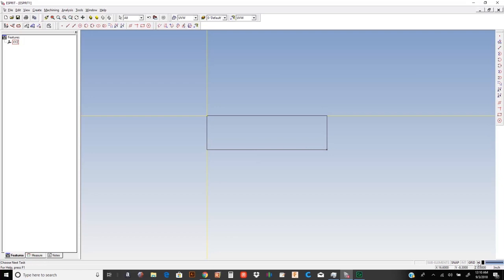And you want to go select a toolpath, right? So you go to select it and basically it selects the line instead. With highlight on, you can select that line, and if it says, do you want to select this toolpath, you right click for no. If you want to select the line, you left click for yes.